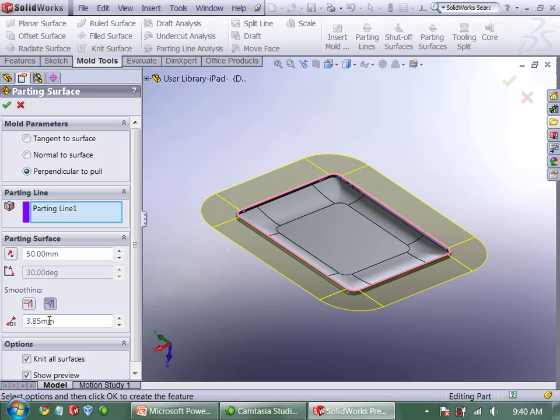This option will create a sharp corner effect in the mold where any surfaces may meet or where the transition may change. So if you want a simple radius instead of sharp corners in a lot of these designs, this is the option you want. You'll notice it's on by default in my case, and the distance is here. This definitely helps a lot when it comes to creating the mold.